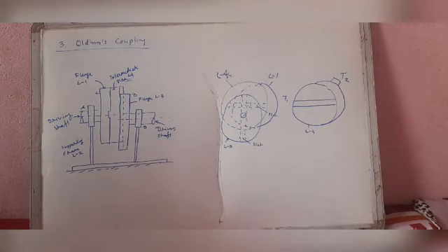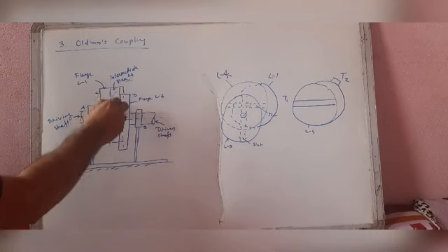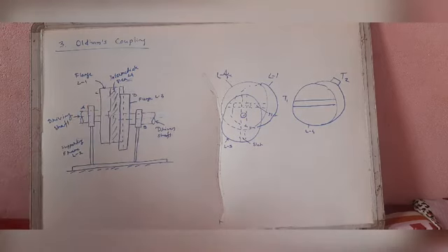When driving shaft A rotates, the flange link 1 rotates and causes the intermediate piece 4 to rotate at the same angle through which the flange has rotated. Link 1 holds link 4 and turns it. It further rotates the flange link 3 at the same angle, and thus shaft B also rotates. Hence 1, 3 and 4 have the same angular velocity at every instant.